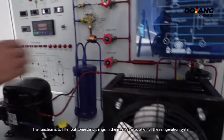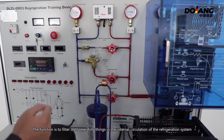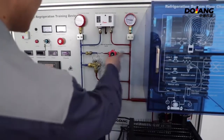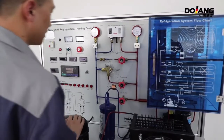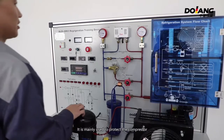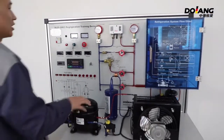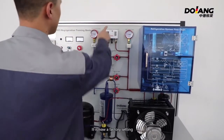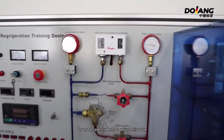This is a filter. The function is to filter out some dirty things in the internal circulation of the refrigeration system and prevent the throttling device from clogging. This is a high-pressure meter. This is a high and low voltage protector. It's mainly used to protect the compressor. You can set a value on it. It's now a factory setting. Try not to ask students to adjust this value.